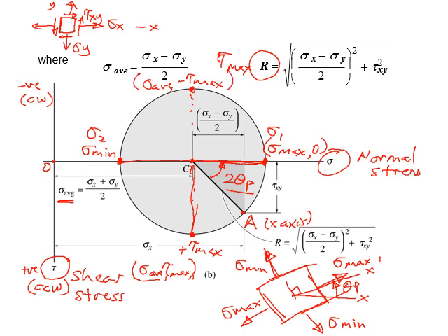Okay, so the values of the normal stresses are the same for both planes, and that's how we can determine how to draw it. And if we want to find the angle, it is this angle here. So if you know 2 theta p, you just minus 90 degrees or add 90 degrees to get to the maximum shear stress planes.